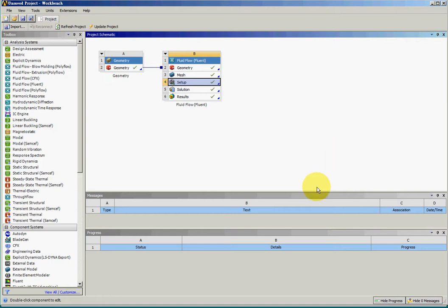For step 4, we define all sorts of goals. For example, global goals for the volume of pressure and velocity, and the surface goal at the inlet for pressure and velocity. And for the outlet, since the pressure is already known, we calculated velocity distribution at the outlet as the goal. And so this is the step 4.